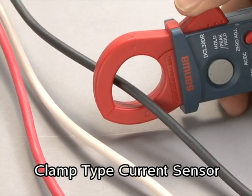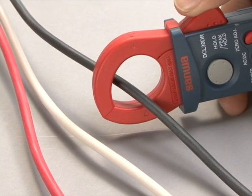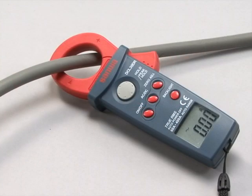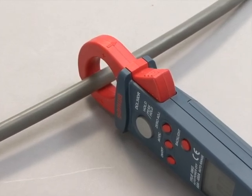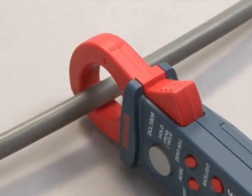Based as it is on the Hall sensor, the current sensor can measure current by disconnecting and insulating and does not require a CT. This current sensor detects the magnetic field generated by the current and can measure both direct current and alternating current. This Hall sensor is used in clamp-type current sensors. Since the clamp-type sensor is built using very precise semiconductor components, this part is especially vulnerable to damage. Handle it with care.